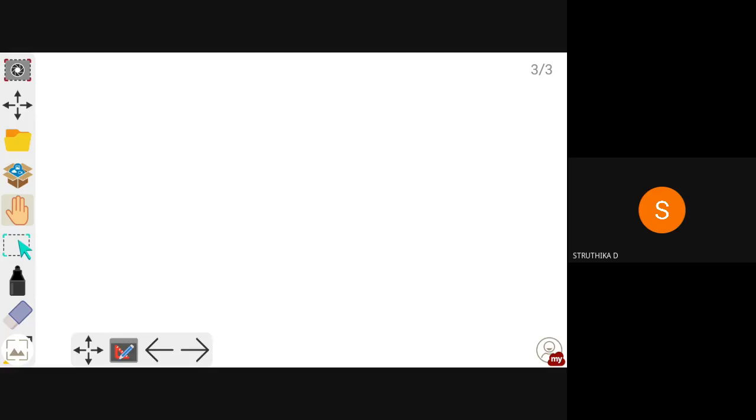Yes, ma'am. So next, I said that the reason you use the enable input is so you can design a higher, that is a larger, decoder circuit using lower level decoder circuits. For that you will be using the enable input.